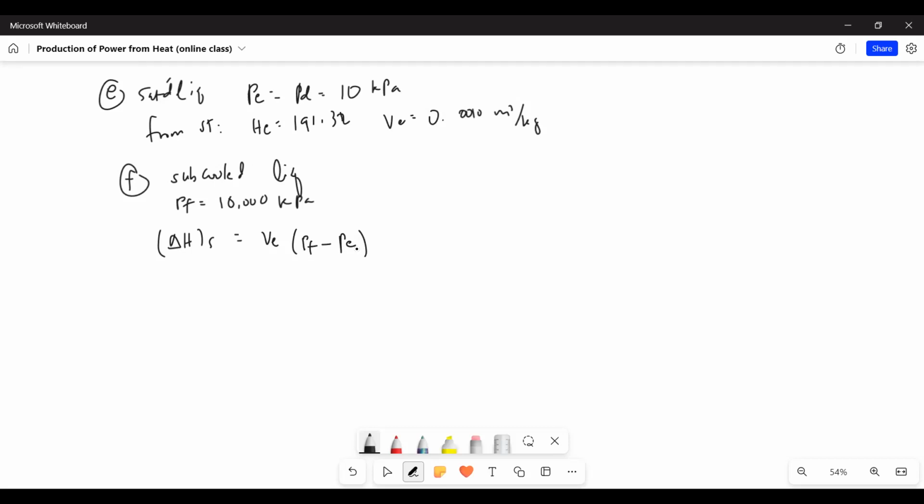And then we can get, substituting the value. So meron na tayong V sub E when we have the PE. Delta HS, we get it as 10.09 kilojoules per kilogram. Now, what is our delta H actual? So, for the efficiency of the pump, delta HS nasa taas, delta H nasa baba. Kasi mas maliit si delta HS. Okay? Correct?